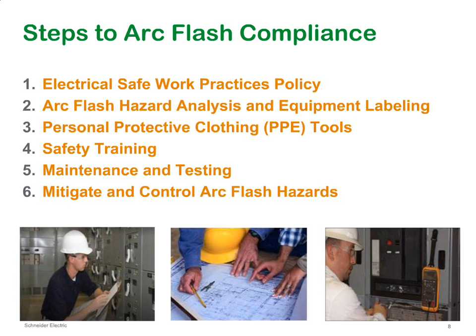So in general, for that worker trying to work on that motor control center, Category 4 is just not practical. Some engineering evaluation needs to be done to see how we can reduce that energy level on that piece of equipment so that it's at a level where the worker can work on it with the right amount of PPE. And this is a subject of mitigation.